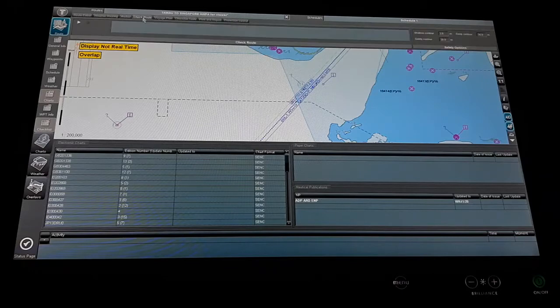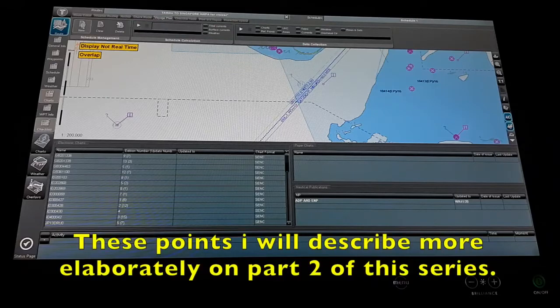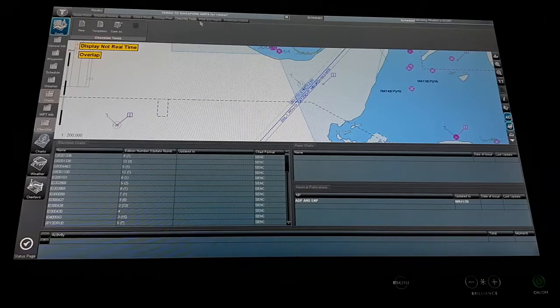After that, we have this check route. This check route option, I will show you during the passage plan, is very useful. Whenever after making any passage plan, we click on this button, so that it automatically checks the route, so that any danger or anything comes up automatically. Also, it's a must to check the route by using this button. After that, we have voyage plan. Same thing like this. Delete, all this option. After that I'll show you checklist tools.